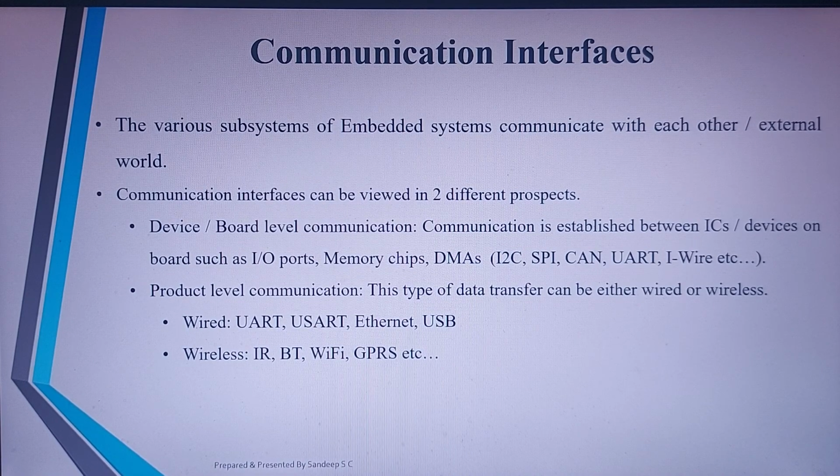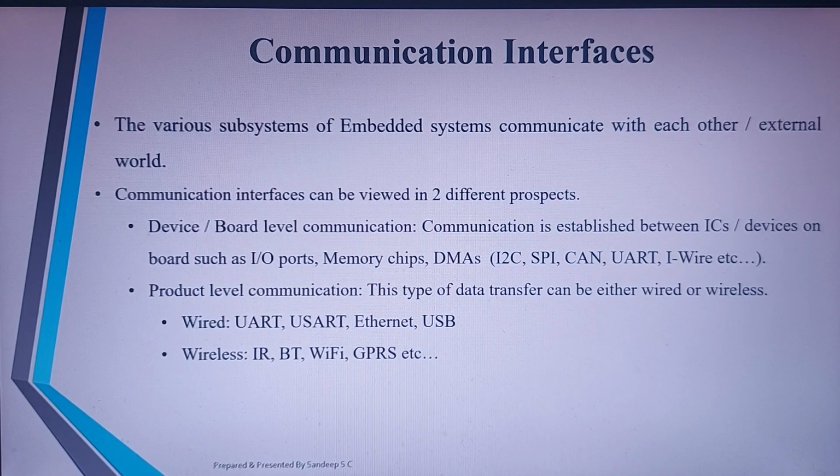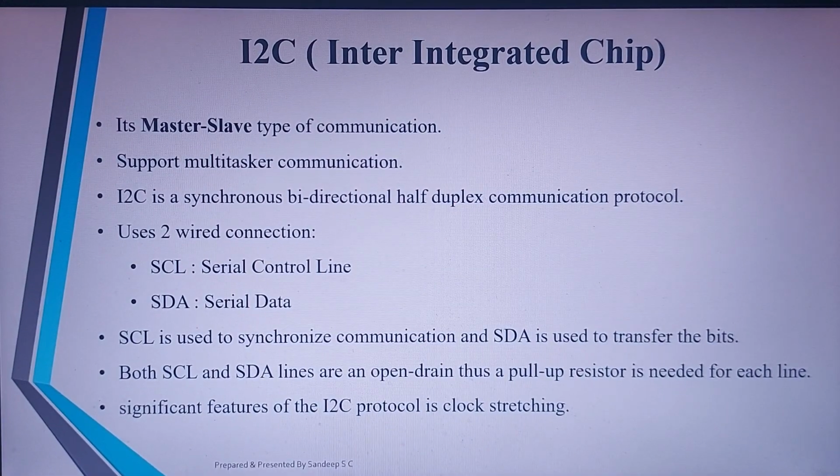So now we will go through the protocols. Not exhaustively, but whatever the important protocols, we'll discuss one by one. The first protocol we discuss is I2C, or inter-integrated circuit communication. As the name suggests, it is the communication between the ICs which are on the same board or a single motherboard. On a single motherboard, we have multiple ICs and they try to communicate with each other.